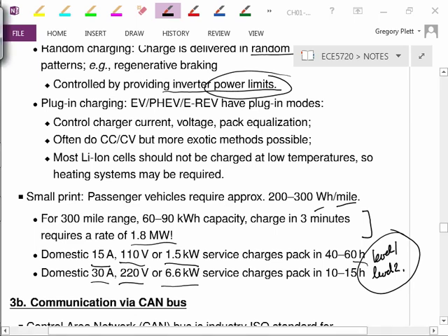So with the Tesla then, you could bring your charging time of your battery pack down to between 5 and 7 or so hours, which is very reasonable if I'm at home and charging overnight, and I could do that any night that I wanted to. And if I'm driving on the road, then I would need a faster charger, maybe a level 3 charger, probably not 1.8 megawatts, but something that's quite a bit more than the small number of kilowatts, maybe 200, 300 kilowatts, something like that, in order to charge the battery pack more quickly.